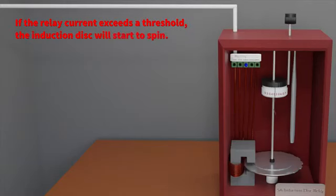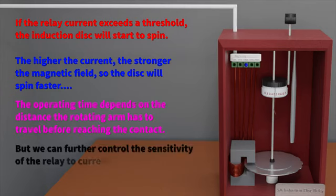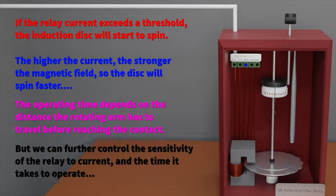Now, we don't want the breaker to operate under normal conditions, so there's a threshold beyond which the relay will operate. And the higher the fault current, the higher the relay current, and the stronger the deflecting force on the induction disc will be. So the relay will operate faster for higher fault currents. We also note that the operating time depends on the distance the rotating arm needs to travel. And we also note that the sensitivity of the relay to current can actually be changed. These final 2 points are really important because they allow us to configure the relay to suit a particular set of requirements, as we'll see.